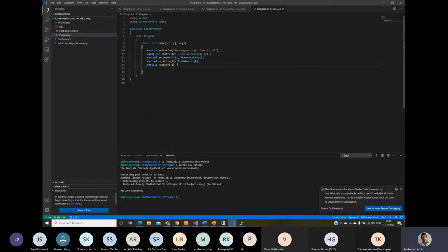And if you remember on my slide, we require root permissions, right? Because we are now going to control the GPIO pins. So we require root permissions. With this command, you'll be able to provide the root permissions. So the /usr/bin/gpio export 22, and we are setting this as out, the mode is output, right? And if you're working with sensors, it needs to be in, right? So this is done.